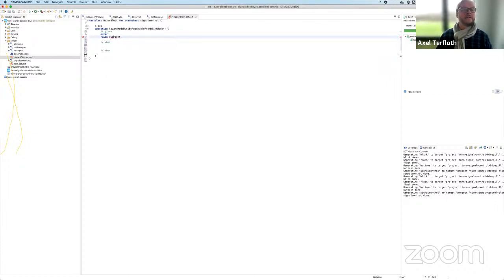Okay, so when we have an active state machine, we require a parameter. We have two blinking modes. One is comfort blinking, which automatically switches off after 3 cycles. The other is continuous blinking. If we pass a payload, the Boolean value true, then it will be comfort blinking. But I want to go with a continuous blink. So I raise the right event,